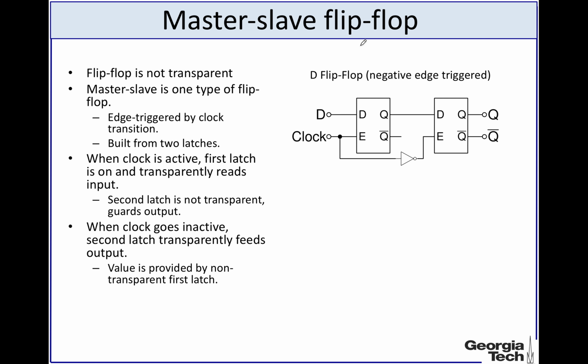is made. So let's say, basically you have two flip-flops. This is the master flip-flop, this is the slave flip-flop, and say this is the output. This output we call Q1. Alright, so let's say your D is like this. So before 0, there was some value of D, and then the clock. So say clock came in here. All right. So if the clock came in here, only after the clock comes in, the Q1 will be able to read the value of D.